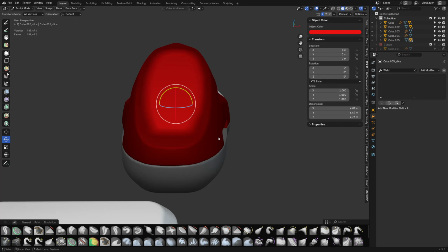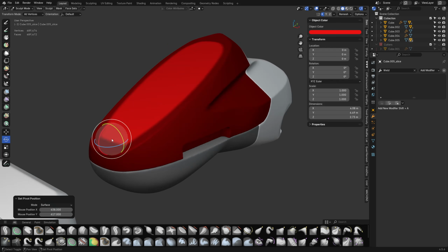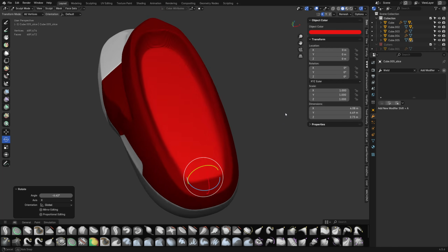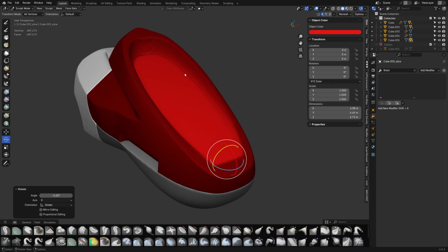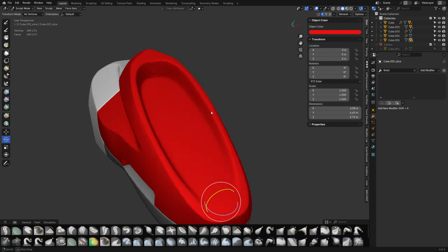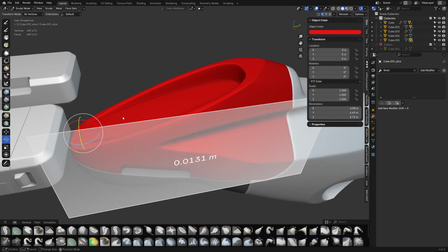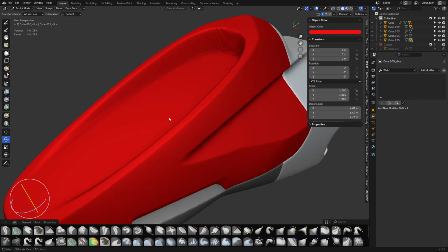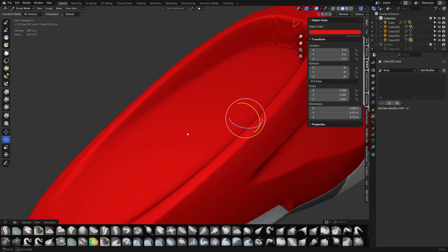I didn't like the scale when that went in. I just think a push down like this might work better. And it's a little tricky to work these areas out in this area. Personally, what I do is just apply it. Or press A, clear the mask, and then I'll remesh to whatever I need it to remesh at. I think I went pretty low there, though. All right, I did. Let's not go that low.